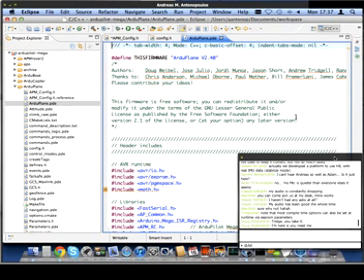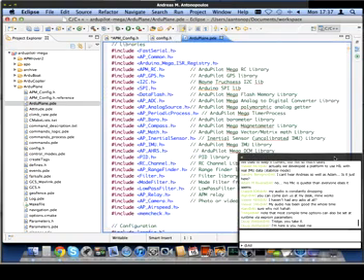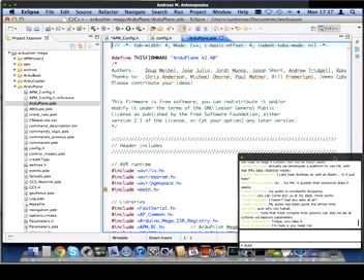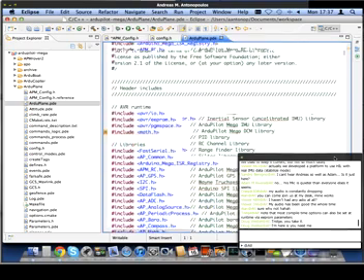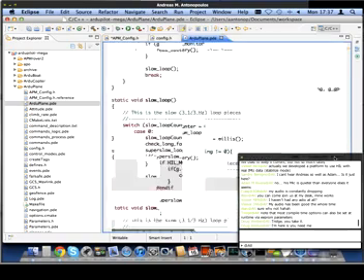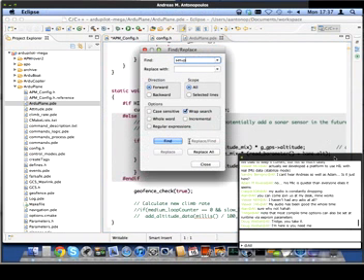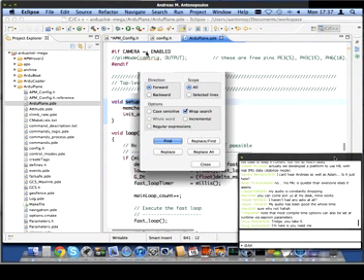Thanks, Andreas. So Arduino sketches. ArduPlane and ArduCopter are all based on the original Arduino development model. And that model starts off by having two functions that are required for every sketch. There's a setup function, which is called once when the board boots. Then there is a loop function that's called continuously. So if Andreas can go to line 641, then you'll find at line 641 there is the setup function.